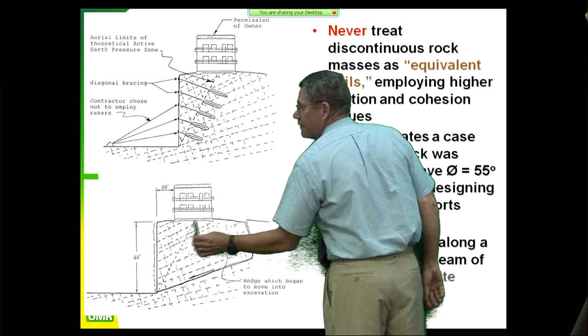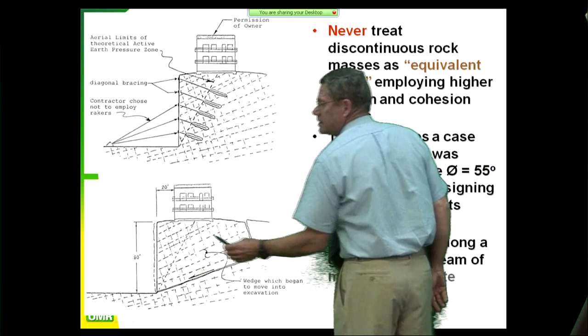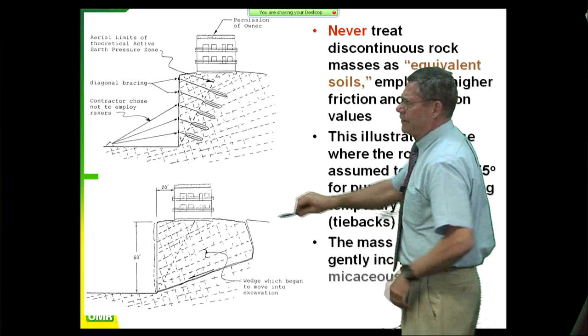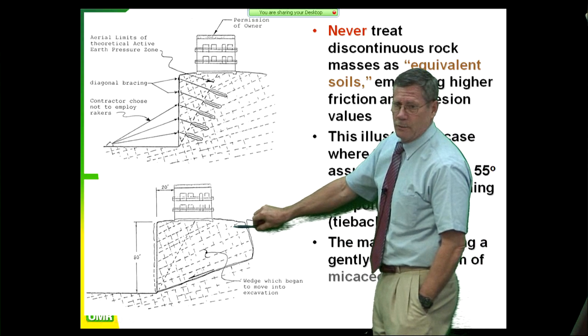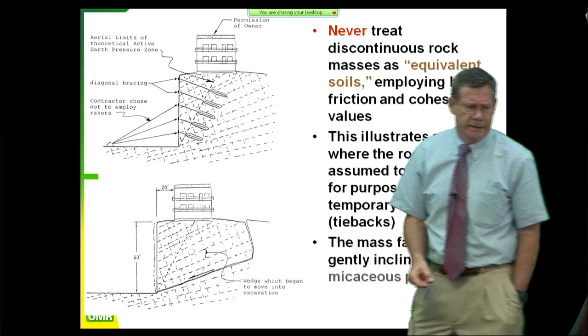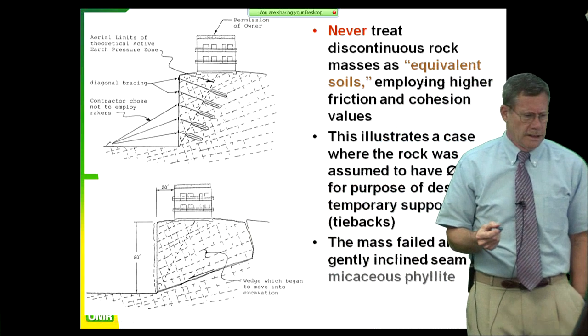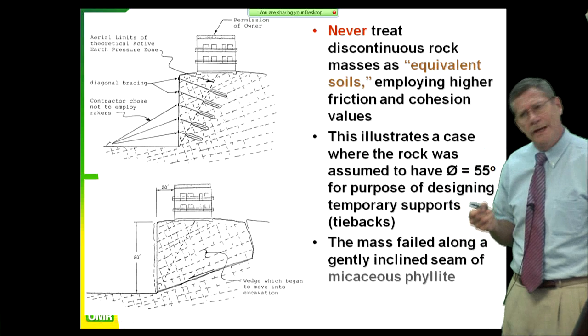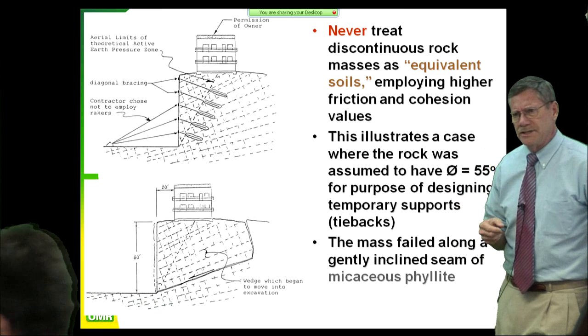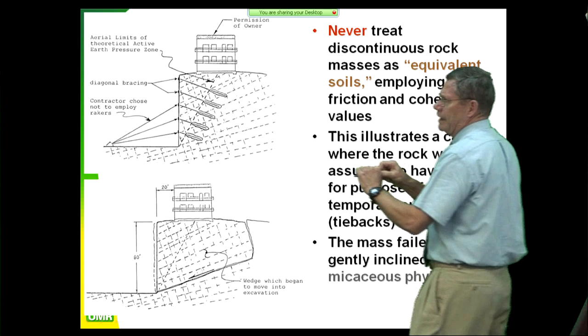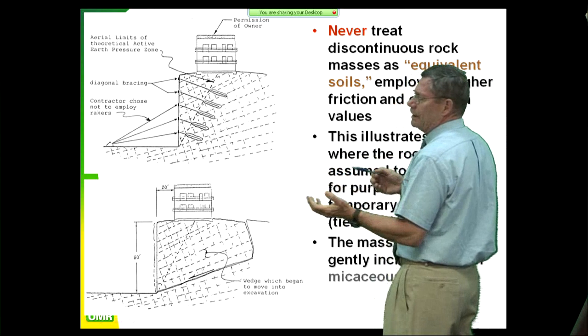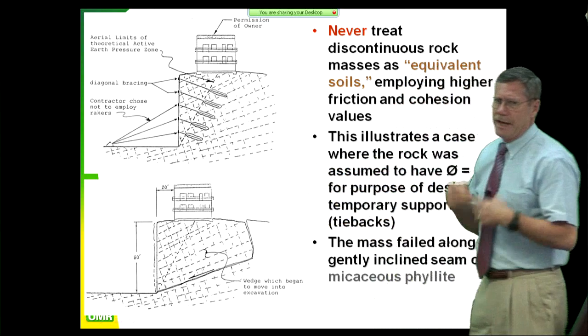And the reason was because right here, when this thing started to relax, this is a very large excavation. If you have an excavation that big, you're going to get some relaxation towards it. And what happened is they tweaked the water line right here, the city water line. Now the city water line is something you don't want to tweak. They didn't rupture it. They tweaked it. Tweaking it means it was a ductile steel pipe. It pulled and it started leaking water, but it didn't make a big noise.